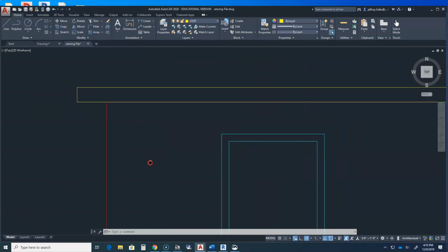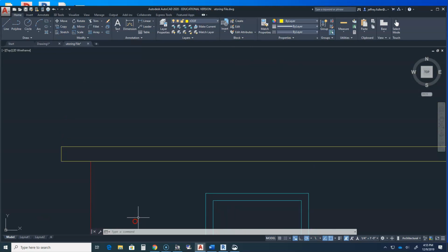Now we need to establish our roof slope by using the rise over run method. Remember that rise over run means that the slope rises a predetermined measurement above the run at a predetermined length. In almost all situations, the run of a roof slope is 12 inches. We will set the rise for 6 inches, so we will have what they refer to as a 6/12 rise